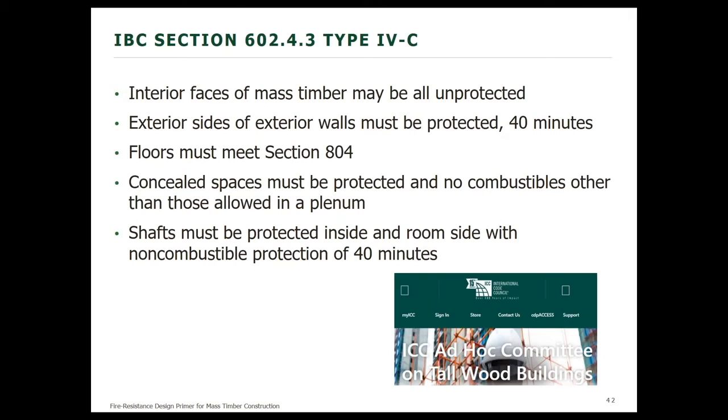What I've provided here are just some of the important points that are significant about type 4C. The interior faces may, in this case, be all unprotected. Exterior sides must be protected 40 minutes. Floors must meet the provisions of Section 804. Concealed spaces, again, although permitted, must be protected. No combustibles other than those allowed in a plenum. And the shafts must be protected inside and on the room side with non-combustible protection for 40 minutes.